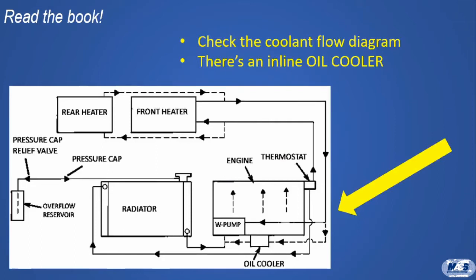The answer would have been apparent if he had checked the coolant flow diagram. It plainly shows there's supposed to be coolant flow through an engine oil cooler in the circuit. It's right by the oil filter, in series with the heater return line to the engine. Disconnecting the coolant hoses at the oil cooler and making a temporary connection to each other restored the system heater function. And when he used his flusher tool on the oil cooler, the debris came out and the system, both front and rear, was back to normal.